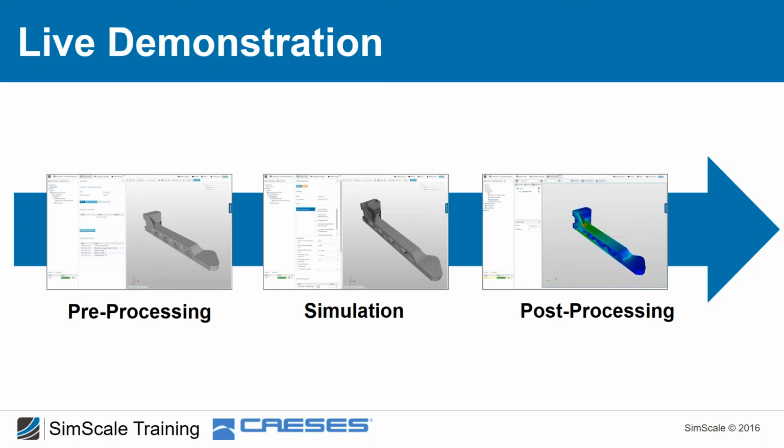And it only means that you have to divide your existing model into small tetrahedral or hexahedral elements. And these elements are later on like a mesh. That's the reason why we call it mesh. You can see it here in the middle image a little bit. And for every node of this mesh, displacement, etc., and stress are calculated, and not between these points. This step is important because you have to define which accuracy, with local accuracy, you